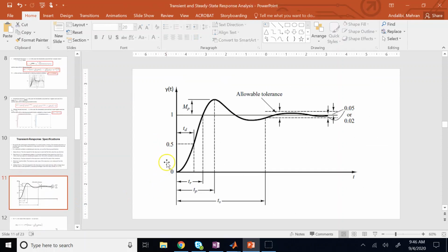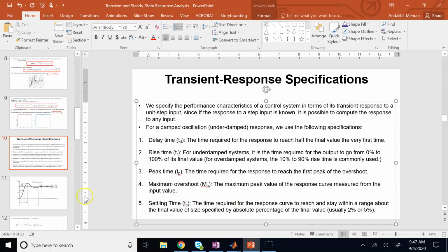So in general, if this is an underdamped behavior, you start, here the initial condition is 0. It's not always 0. But you start going, you overshoot, undershoot, and finally converge. It takes forever, but practically, we don't say we need infinite time to converge. As long as you are within a range around the final value, you say, I have gone there, and we call it the settling time.